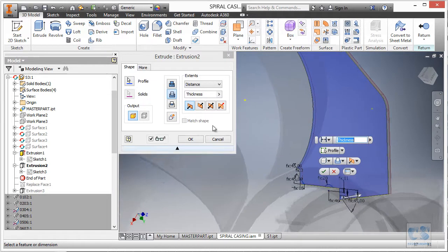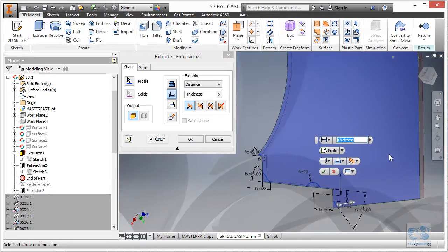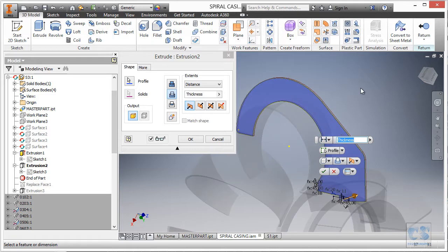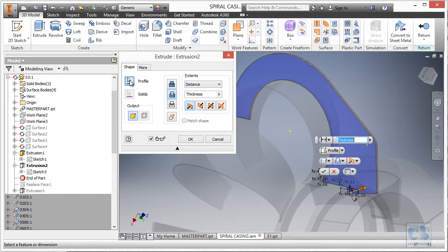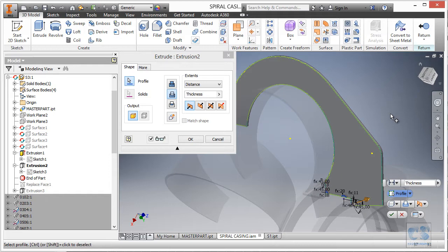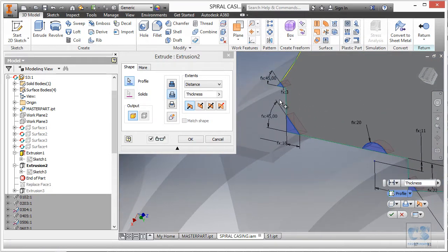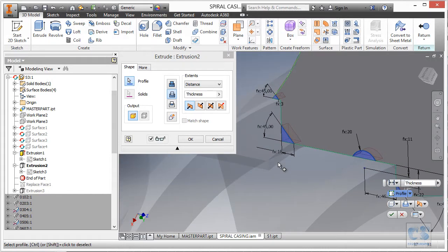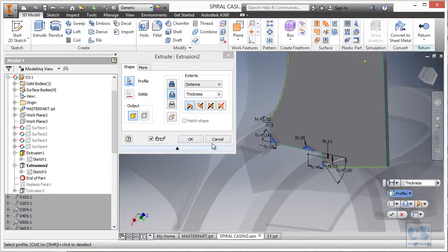We're just going to finish the sketch and edit this extrusion tool to see what is going wrong. And now we can see that the entire face is selected and the part is entirely cut. So this is why we had nothing on the screen. So we are going to make sure that we deselect this whole area, and the way to do that is to make sure that we have this profile selection active. Then we will press the control button down, then click on the face, and as you can see, the area is no longer selected. We will make sure that only the region for the weld gaps are selected. We should have 4 of them. Okay, they are all selected, then okay.